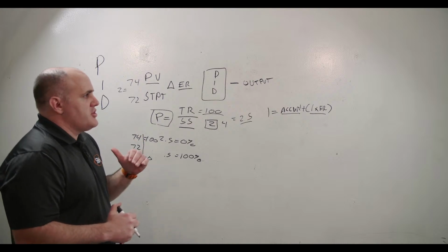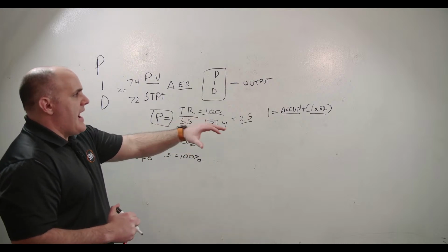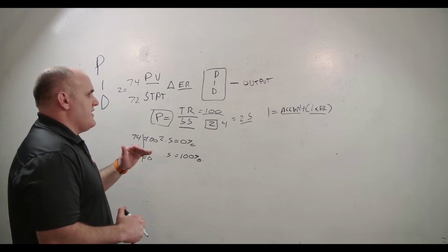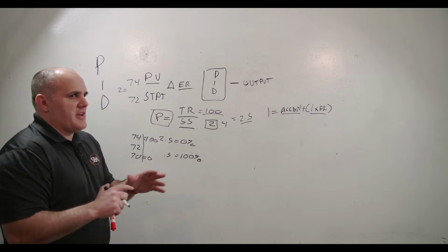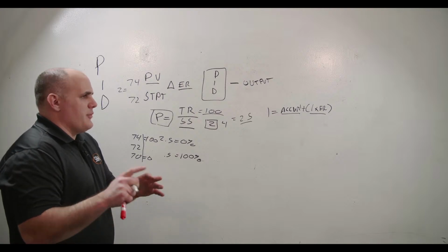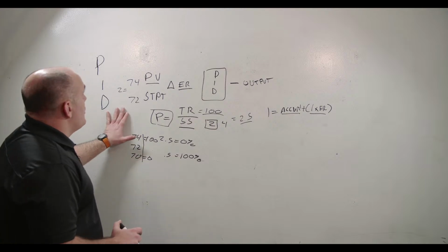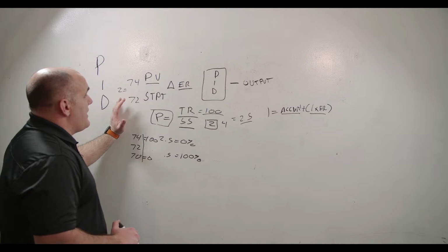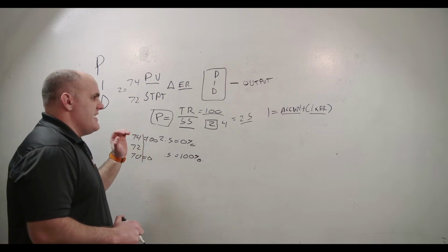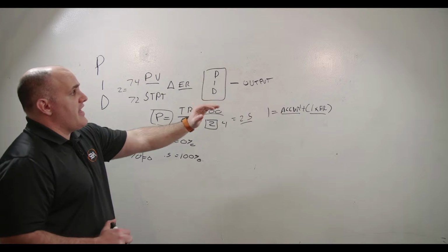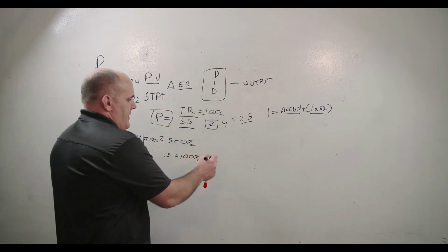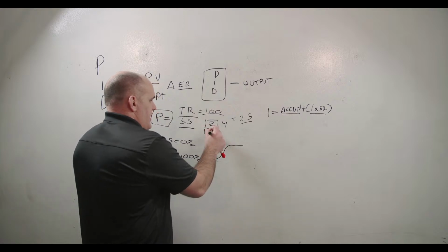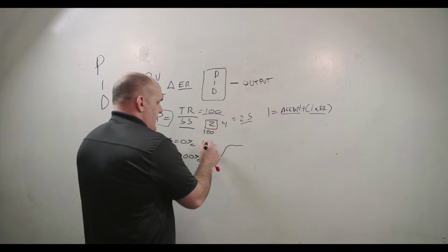In pressure, we have overshoot, so we'll talk about I and its effect there, in that it can help us be responsive, and how we might use derivative there. I know I'm talking about stuff we haven't got to yet, but we'll get to that. So we're talking about accumulated I, and what it allows us to do, especially on slow acting loops, is it gives us that little oomph to move that output up. We would get kind of stuck, if this is 0 and this is 100%, at that 50%.